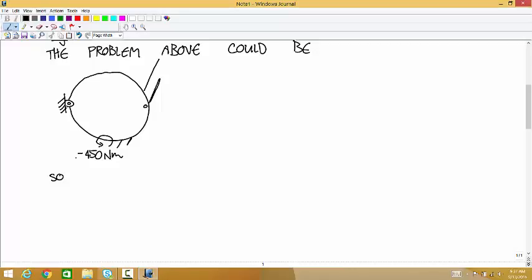And what we saw is that surprisingly, when you're dealing with a couple, it doesn't matter what your about point is. So no matter where on this body we chose the about point, we would have this couple of negative 450 added to the moment equation, whereas the moments produced by this force or this force would change depending on what the about point is. Yep.